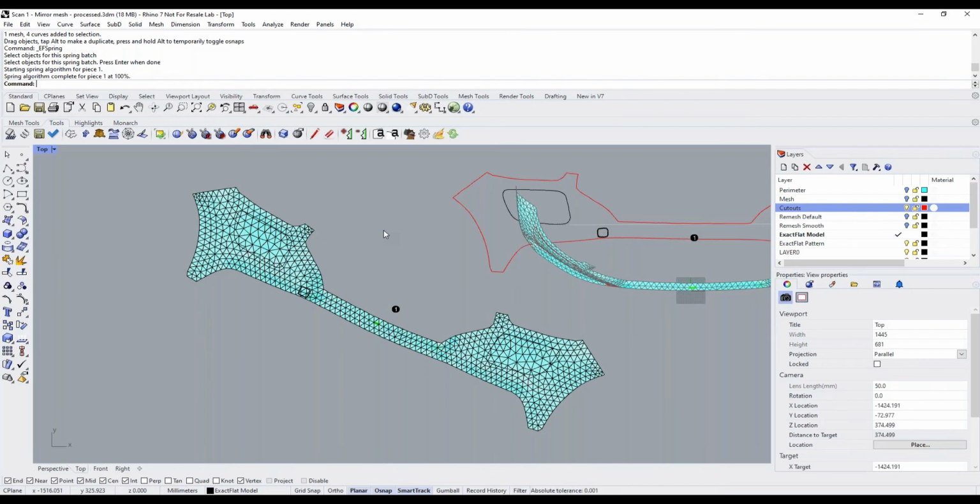Now, with respect to edits, I'm not sure what edits you're talking about. If you're talking Adobe Illustrator, and for example, you're making edits like graphics and things like that, the graphic edits are not backwards compatible into a DXF. You'd have to create your output file from Adobe Illustrator and then take it from there. We can make edits to the 2D file here, so you can put in a dart or a cutout in 2D. You can do the darts or cutouts in 3D, and in fact, they're usually done in 3D, and then they're automatically sized when you flatten the part.